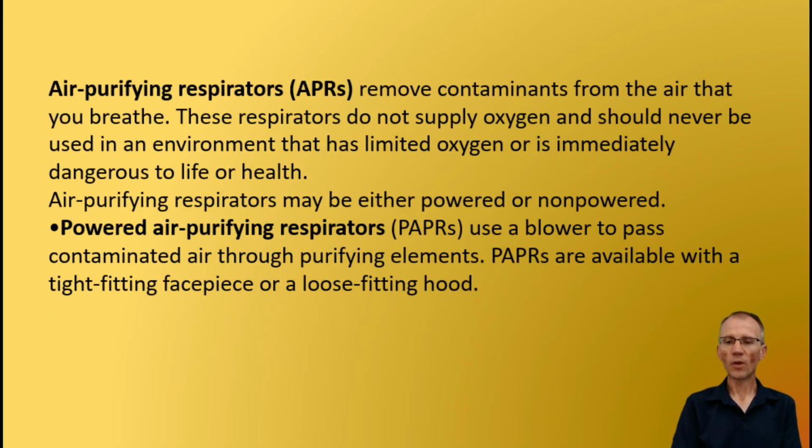Air purifying respirators, APRs, remove contaminants from the air that you breathe. These respirators do not supply oxygen and should never be used in an environment that has limited oxygen or is immediately dangerous to life or health. Air purifying respirators may be either powered or non-powered.